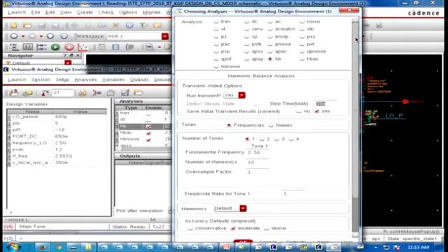It will first predict, because it will ask the user what the predicted value of the input frequency of the RF or local oscillator is. Then it will go for at least some stabilization time. Then it will check whether that is the perfect time period or not. If it is satisfied, then only it will start the harmonic balance technique.